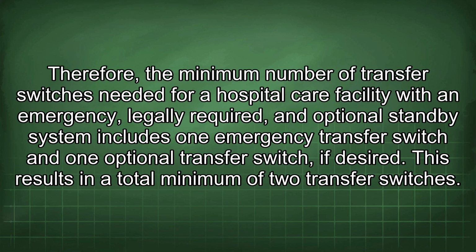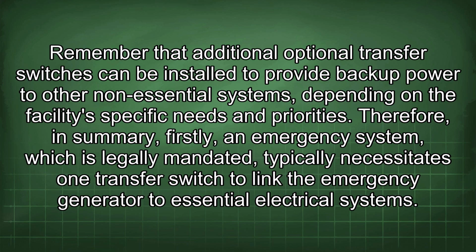Therefore, the minimum number of transfer switches needed for a hospital care facility with an emergency, legally required, and optional standby system includes one emergency transfer switch and one optional transfer switch, if desired. This results in a total minimum of 2 transfer switches. Remember that additional optional transfer switches can be installed to provide backup power to other non-essential systems depending on the facility's specific needs and priorities.